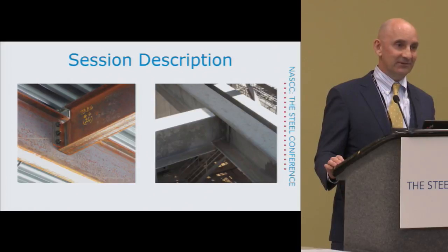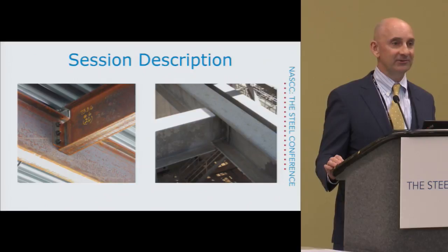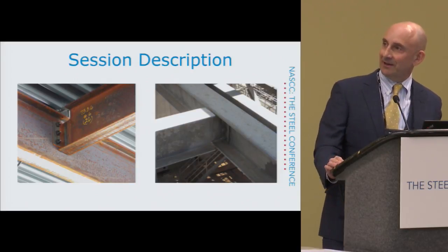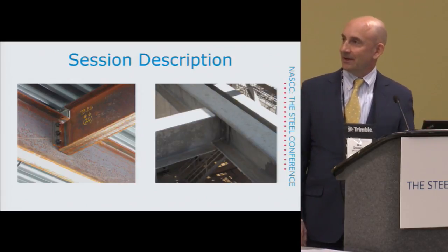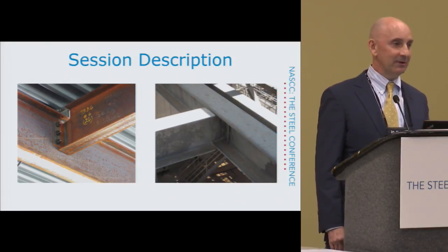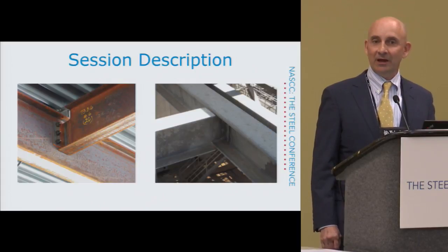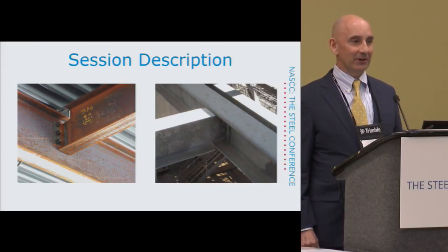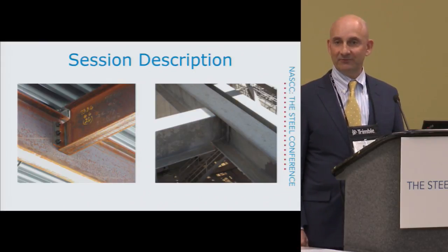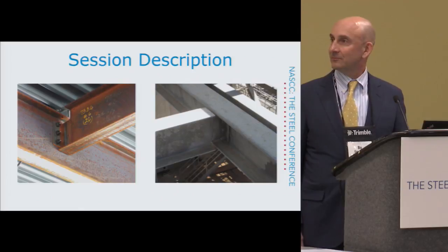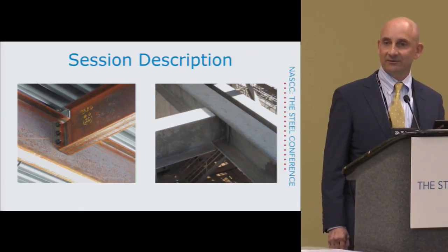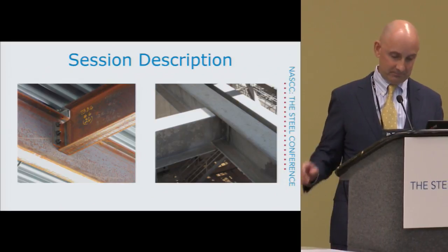So it raises that top of steel of the supported beam, of the cope beam, 2.5 inches from the supporting beam. And on the right-hand side, you see a galvanized double cope beam, and that will typically happen when you have two beams that are of equal nominal depth framing to one another, where you have to cope the top and the bottom flange. And that's a picture that I actually took about 2 weeks ago on a site of an industrial plant.